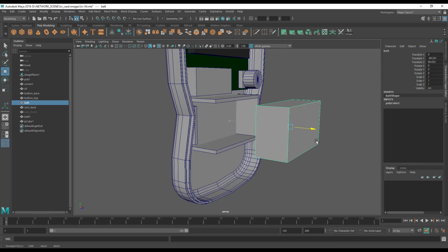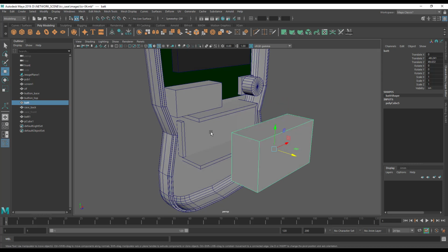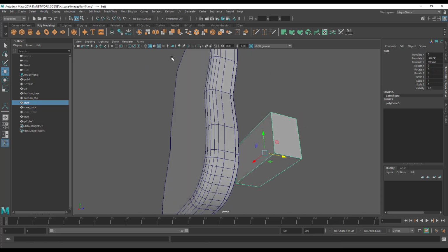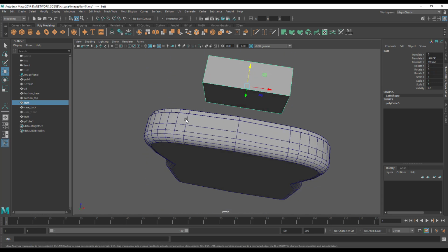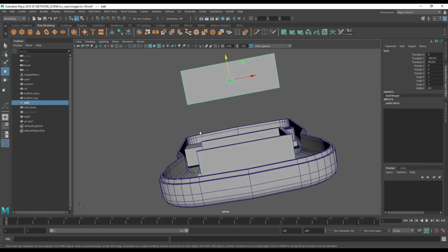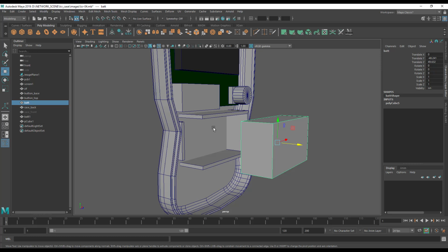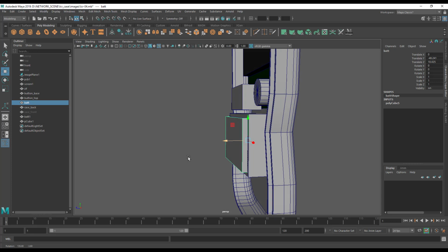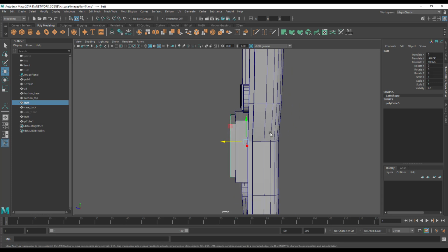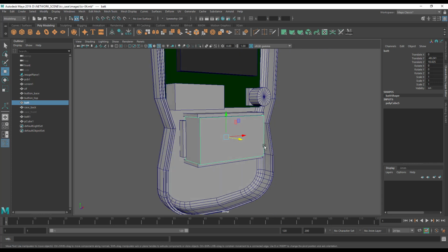Now we could design some clips to go over the top, but that would require printing with support. Obviously when I print my case, I will print it so this is the flat side, and if I have things jutting out this way, we'd need a support from the bed. Now that's not the end of the world, but I'd rather avoid that at this moment. What I'm hoping is the battery will be close to the limit of the maximum thickness that we need, so the front of the case will actually help secure the battery in place.